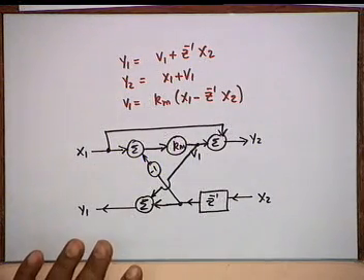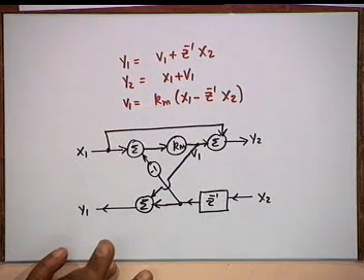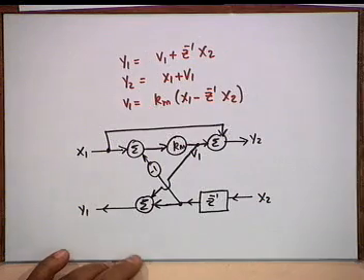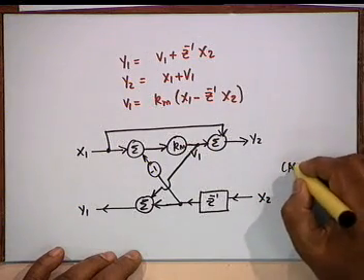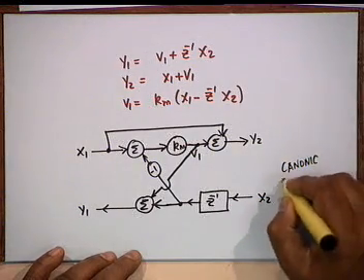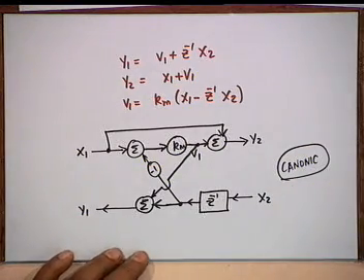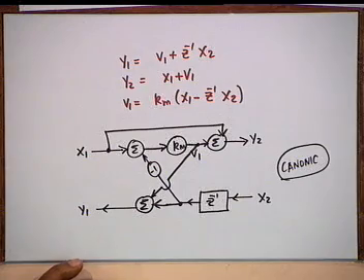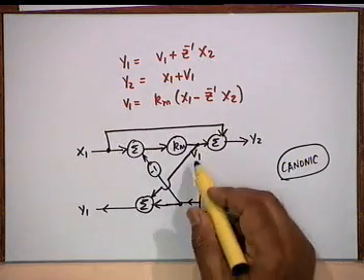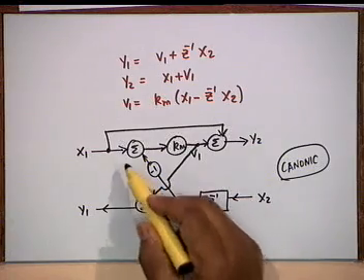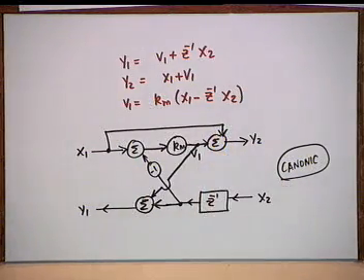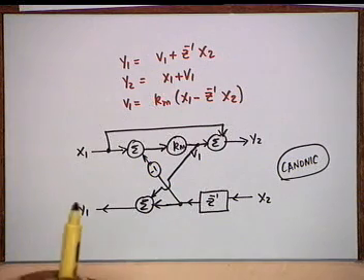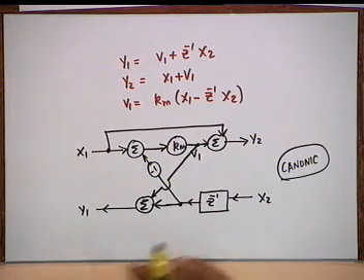Is it okay? Single multiplier, single delay, and therefore this is indeed a canonic structure. One reason that I guess why this structure is not popular in comparison to the two multiplier structure is because there is a crisscross here. There is also another line here. Perhaps this poses problems, I am not a VLSI expert, perhaps this poses problems.